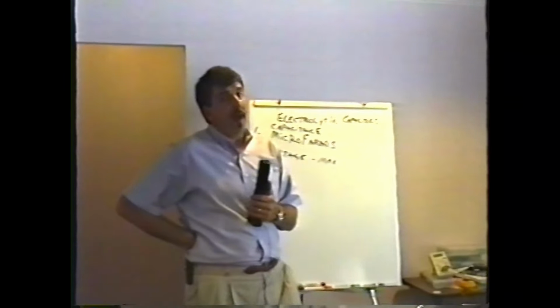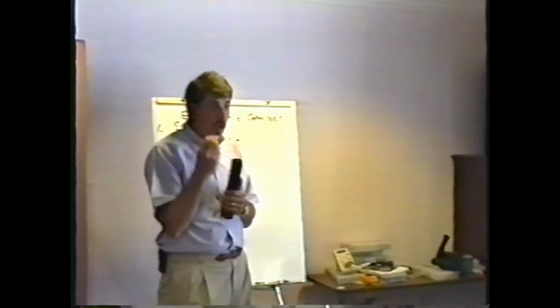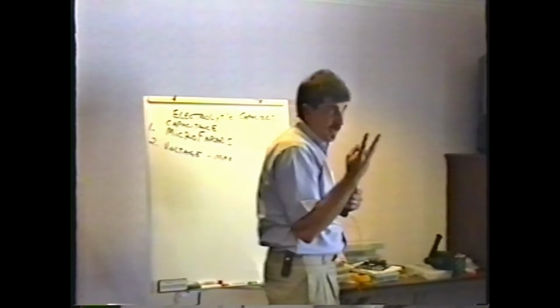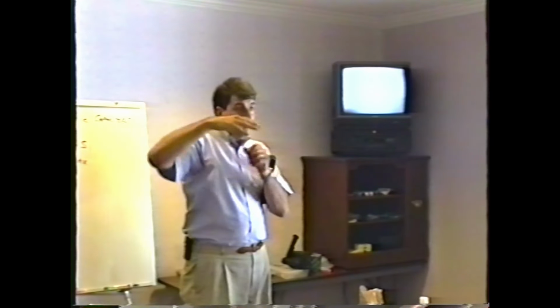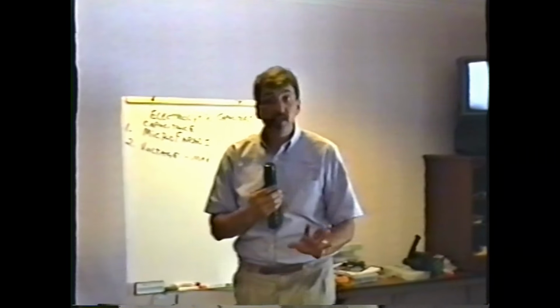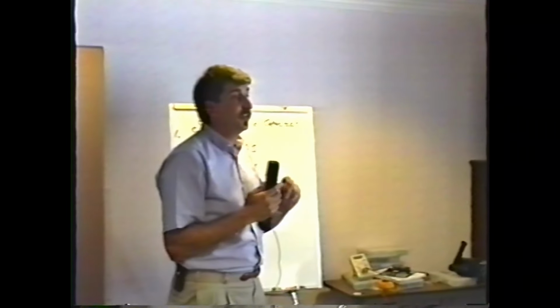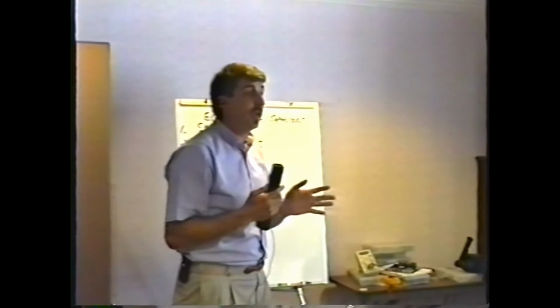Now, capacitors. If a capacitor looks bad, and again, the three criteria: is the top domed, is it curved at all on the top? Bad. It should be perfectly flat. Is the plastic coating on the top shrunk down at all? Bad. Or is that vent busted open? Obviously, that's bad. Then you definitely have to replace it, but sometimes capacitors look good when they really are bad.